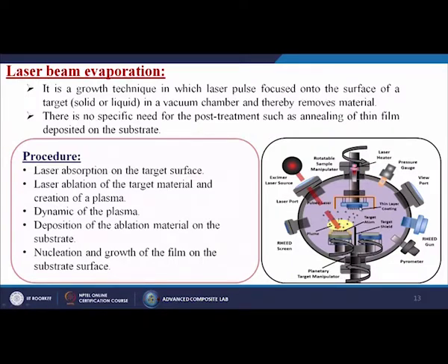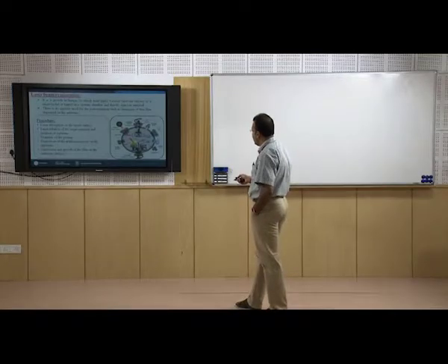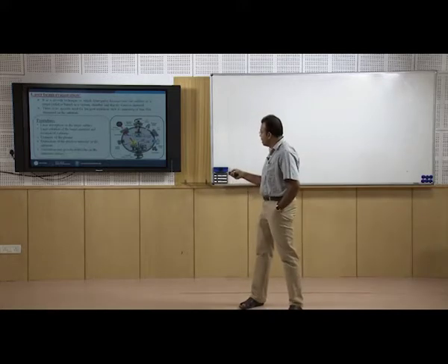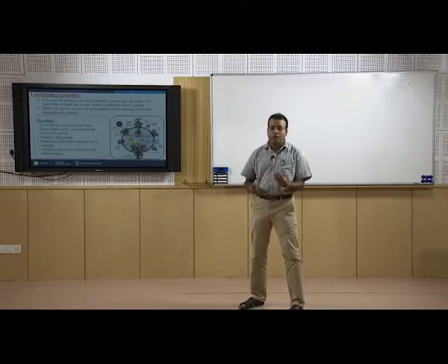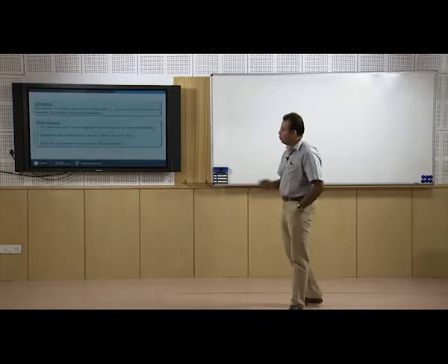And this is the total experimental setup design, where there is a viewport so that you can see whether the target material is being hit directly by the laser or not, whether the evaporation is taking place or not, whether the material is depositing onto the substrate or not. Not only that, here we have the pyrometer, and a port where we can change our target material. This is a rotation, so you can put one or more target materials at a time, so that you can do the coatings by a layer method onto the substrate itself.